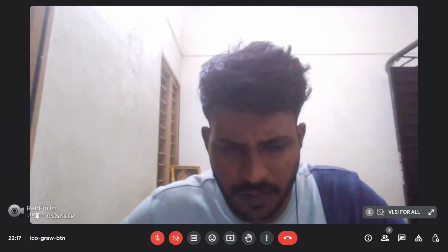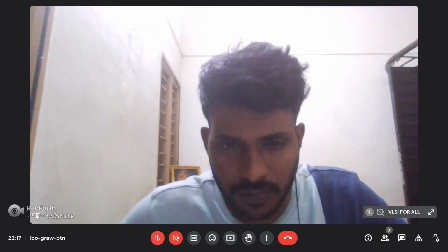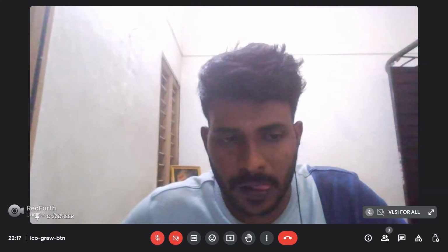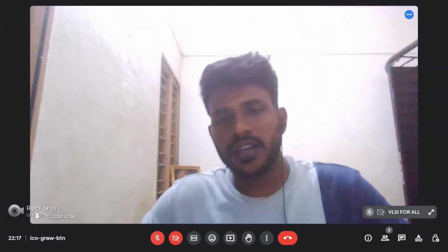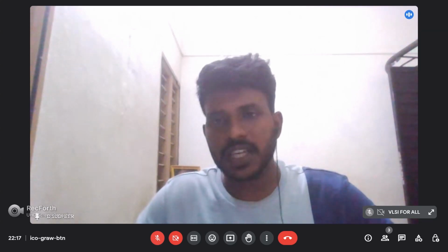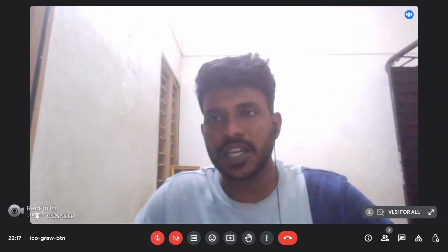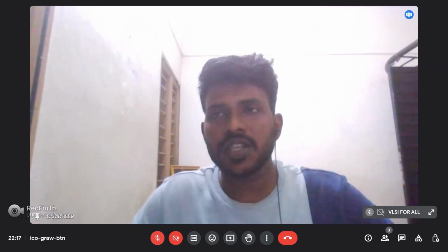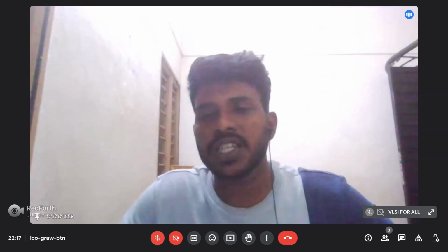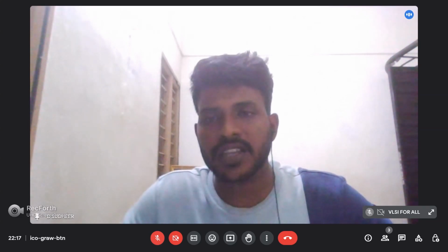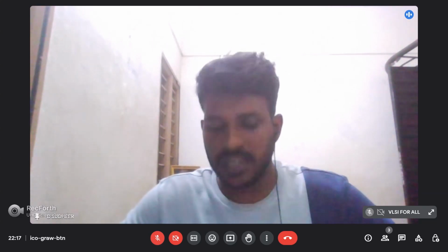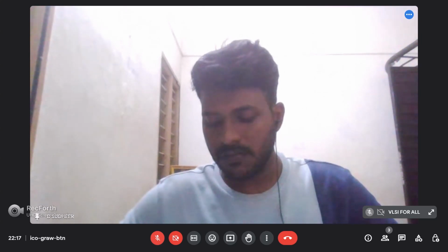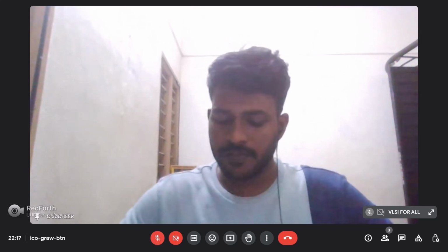So how does it arise? We want to give the clock at 0 seconds, but it comes at one picosecond. The clock starts at 1 picosecond. How does that happen? Due to the wire delay, it may occur, sir. That's why we use trees to reduce the jitter. We use trees like the H tree, X tree, I tree, to get everything the same.